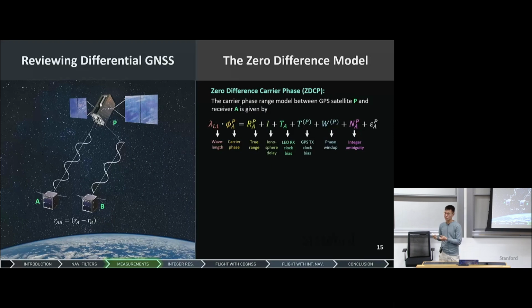And your times are not synchronized with GPS. In reality, they're not perfectly synchronized. So at the very first step, not only do you need to estimate your XYZ, you need to estimate your clock bias. How far off are you from GPS time as well? So this is captured in this term over here. My laser pointer, I don't know if there's parallax. Yes, this term here.